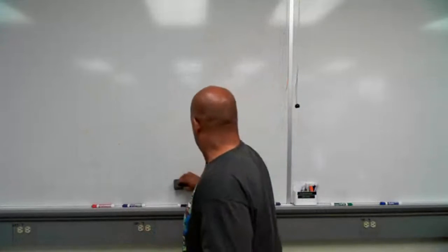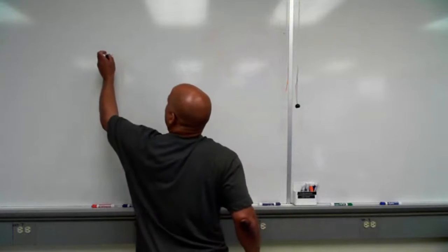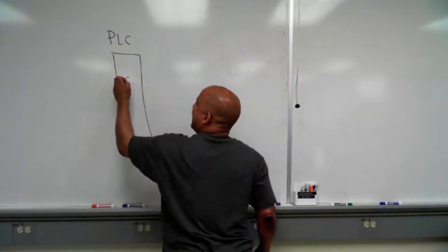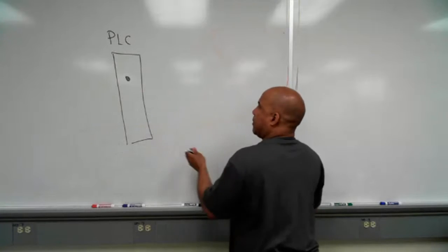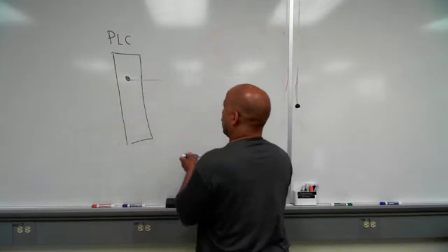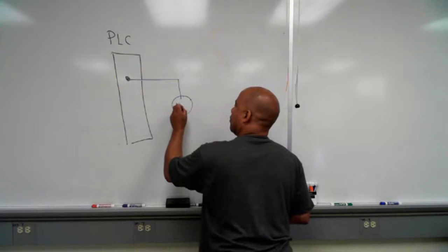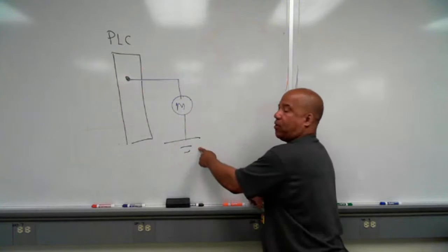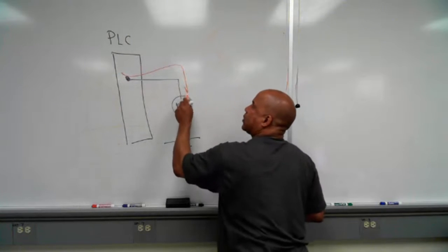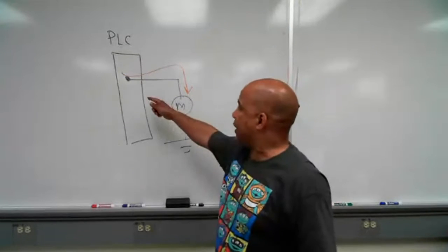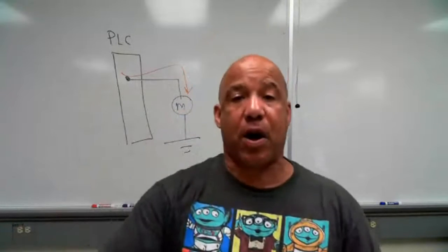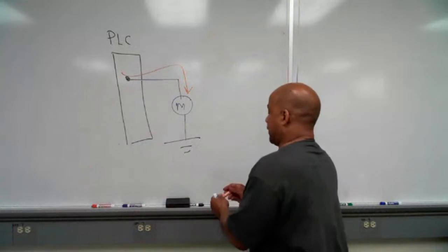Say you're controlling some kind of device. Well, one way to hook it up is like this. You've got your output module, here's your PLC output module. And connected to the screw terminal, you've got some kind of device, maybe a motor. Here's my motor. And if you don't know, this symbol is just short for ground. So in this scenario, current is going to flow out of the PLC into the motor. I'm assuming that's a small motor and this thing can put out enough current. So this thing is giving current to something. It's sourcing current. It's the source of current. This is a source.